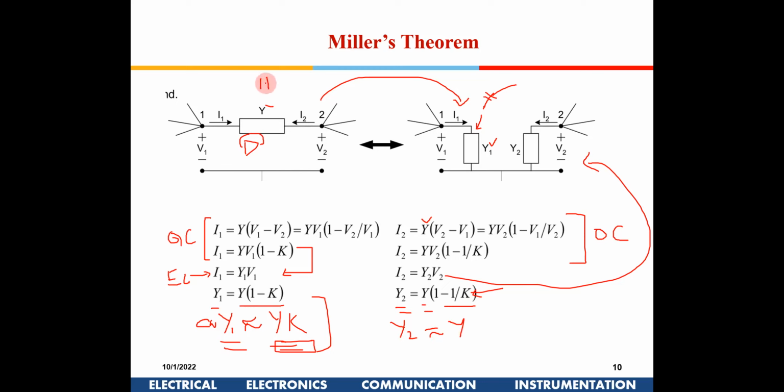So if it is a capacitance between the input and the output, generally for a CS amplifier it will be the gate to drain capacitance. Towards the input side, it will get multiplied by the gain, and the same capacitance gets reflected at the output, but at the output it doesn't get multiplied by the gain. It will just go just like that. Is it okay till here? Yes, probably a little bit vague out here, but once we see the circuits, it will be clear. So these are the basic two approaches to solve high frequency analysis of circuits.